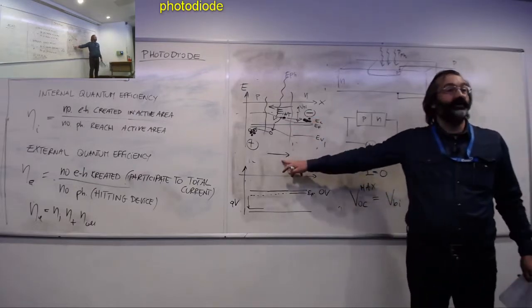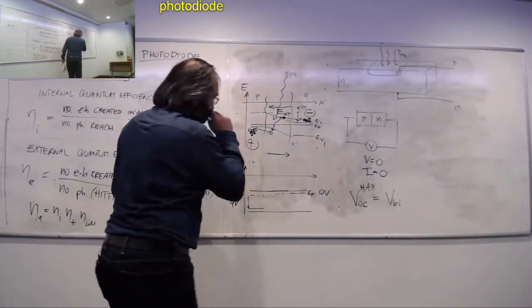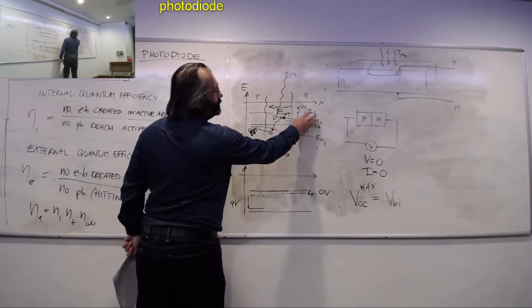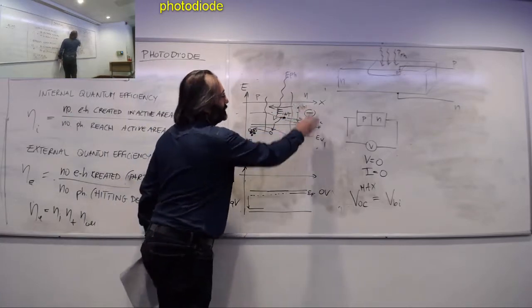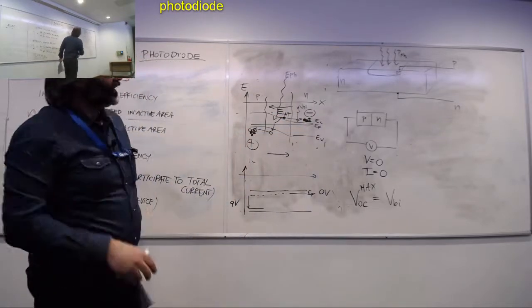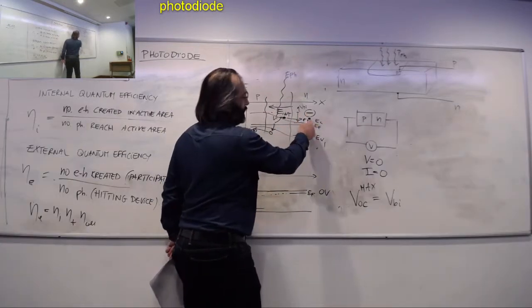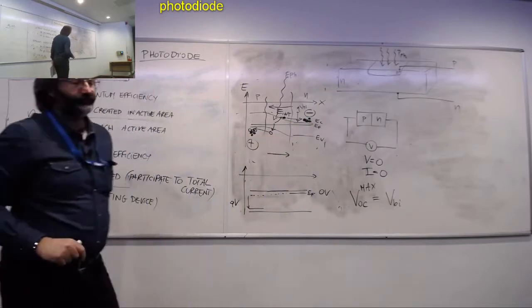In this point. Very, very rapidly. When there is no light, here there is an amount of charge that is the one due to the fact that the semiconductor is N. But if I start to shine light, there will be extra electrons that go there because of charge separation, extra holes.